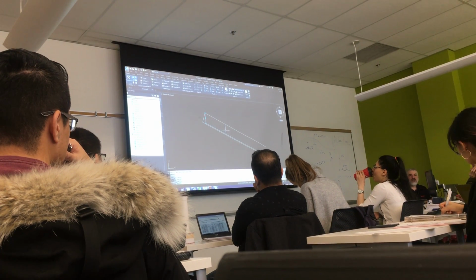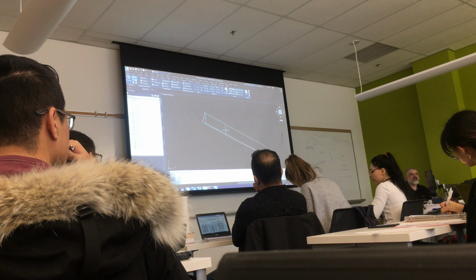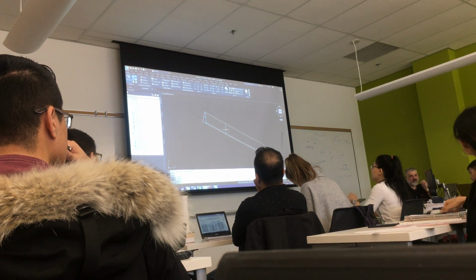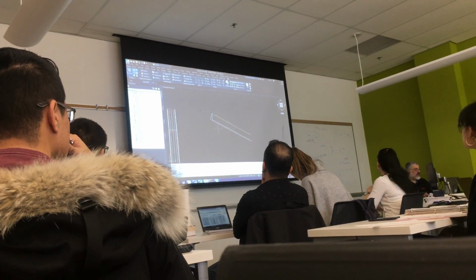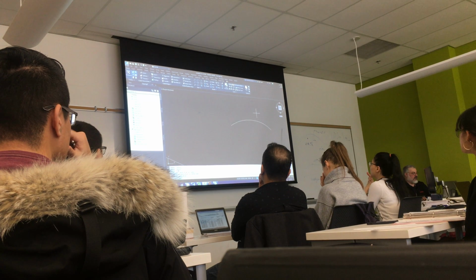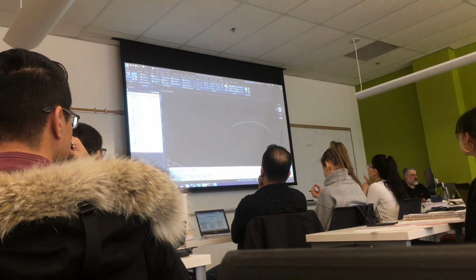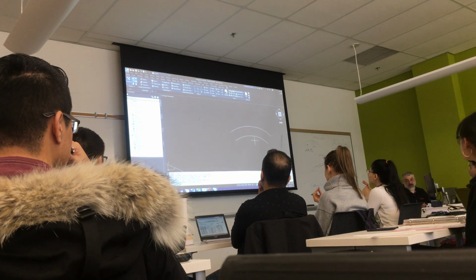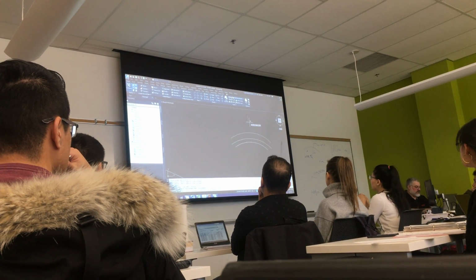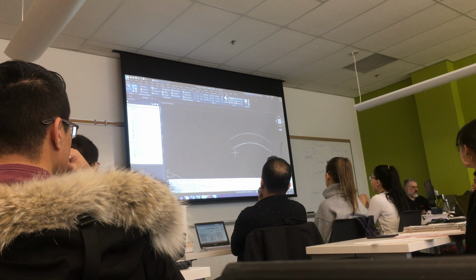It's wrong. The only time you can use an offset is if the thing you're offsetting is flat. Then the offset and the vertical copy is exactly the same. Otherwise, it's different. And think about curved items. If I draw an arc, if I offset that by 10 meters, I actually get a different radius. If I copy it straight down, 10 meters, it's the same radius.